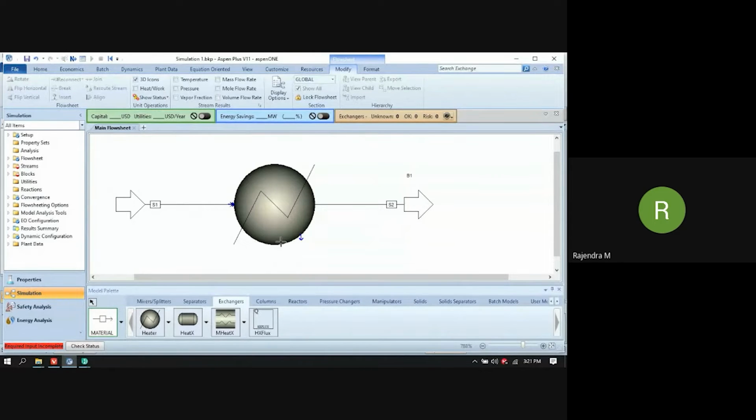Okay, and there is another stream like water decantation. Water decantation means a kind of free water when we are having immiscible phases, and one of the phases is water. In that case, we can decant the water continuously from the heat exchanger. Like a condenser, you have the decantation stream, decantation process.